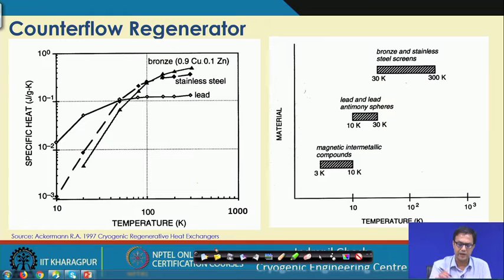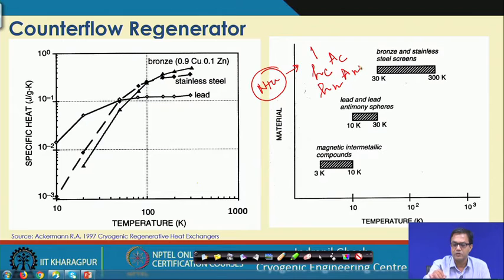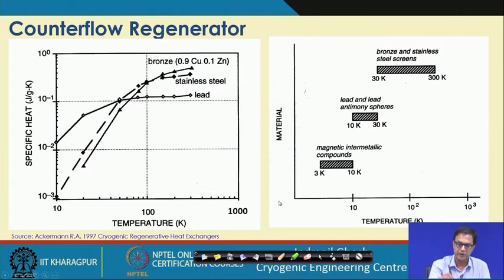Other than that, if we look into the NTU part, to make the NTU high it is obvious that we should have a high heat transfer coefficient for the cold side and the hot side, and then obviously you have to put more surface area associated with both the cold and the hot fluid. So, with this we will move to the design part once again.